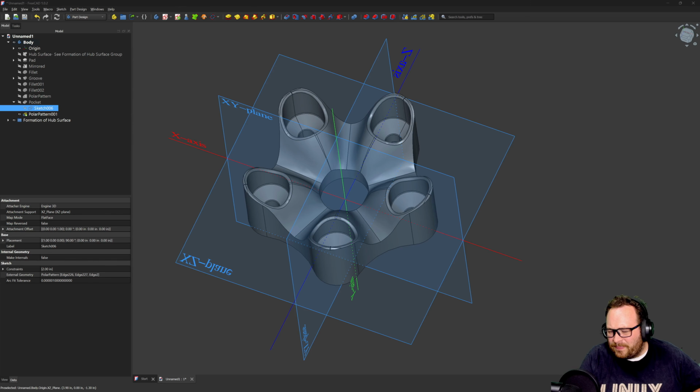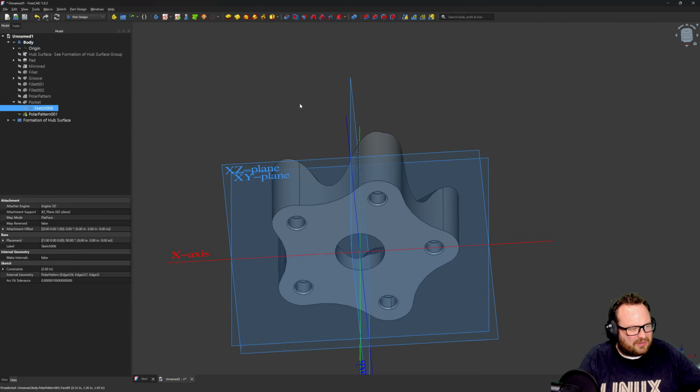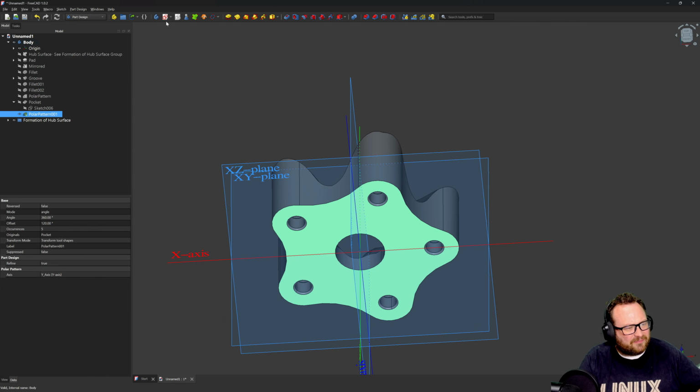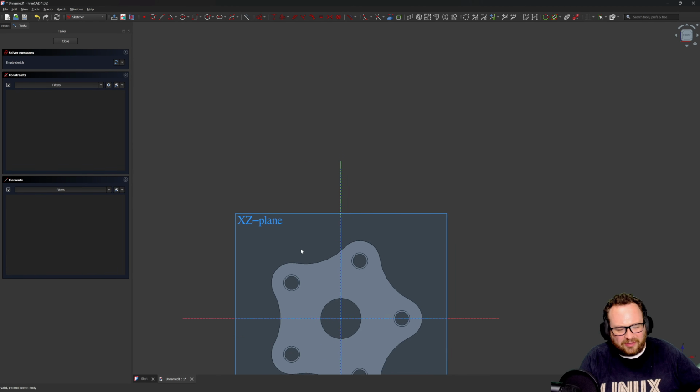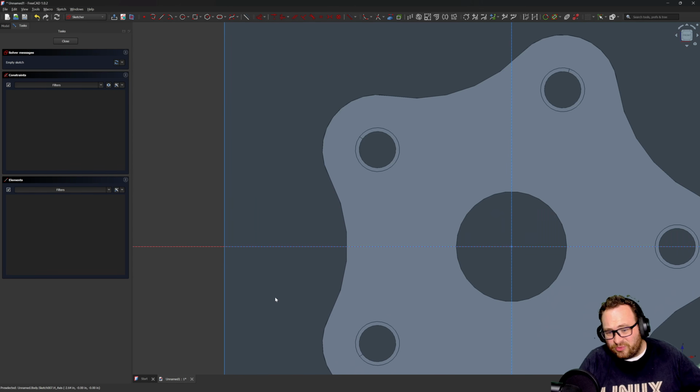Next, I want to make a sketch of a spoke, and I'll have it be on this bottom face. And so we're going to start forming our spokes. Now I'm going to use, again, tools that are not readily available in Part Design to make this spoke. So I'm using the Part Design workbench tools, but then I'm going to have to go to the Curves workbench or something else. And that is where that body, the spoke body, isn't going to fit in my Part Design body anymore. So that's when we're going to use our groups.